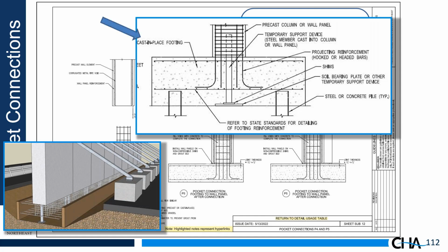Very simple cast-in-place design. It might take an extra day to build this as opposed to using full precast for the footing, but it's a much easier detail to execute in the field, and it's a much less expensive detail, and it really is still quite fast. The detail on the lower left is a sketch showing how this might work for, say, a wall pier construction.